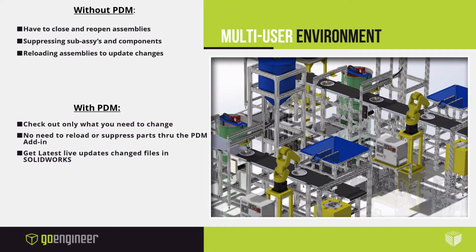But if I've got the main assembly checked out and then a user checks out something underneath it, does everything just automatically update on the screen for me? How do I get things to update so I can see what changes have occurred? Sure. Inside the PDM add-in interface, it will show you who checked out the files in those substructures underneath. As they check in changes, it will flag them in a red color and show you that you have an older copy of the file. Then inside of the SolidWorks interface, all you have to do is right-click and get latest version, and it will pull those changes across the network to your live assembly. So you can get true simultaneous work.